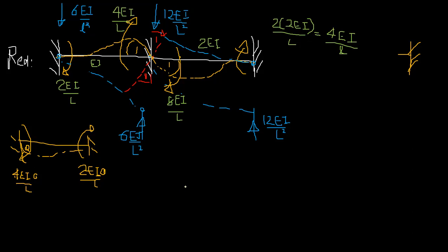So your M, bending moment, due to unit rotation. That means force due to a unit displacement. What did you do? You had a theta rotation at B and you made it 0. Now you add a unit displacement and calculate the force. If your displacement is unit, this is a unit value 1. That means the force is stiffness. That's why we call it stiffness. So stiffness 1 is going to be this bending moment, because we are considering the force. The force corresponding to that rotation is a bending moment. This is in clockwise direction. This is also in clockwise direction.